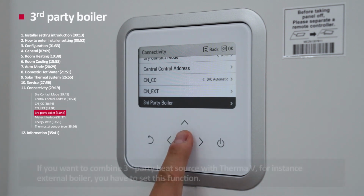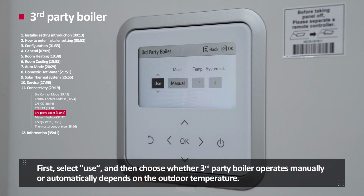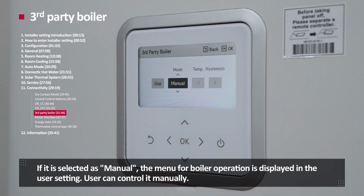Third-party boiler. If you want to combine a third-party boiler heat source with Therma V, for instance, an external boiler, you will have to set this function. First, select Use, and then choose whether the third-party boiler operates manually or automatically, depending on the outdoor temperature. If it is selected as manual, the menu for boiler operation is displayed in the user setting. The user can control it manually.